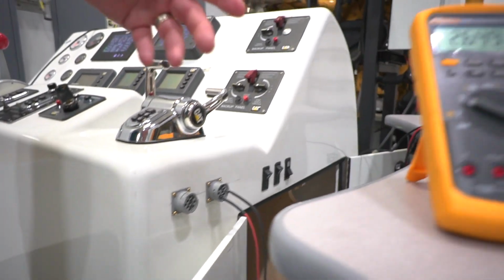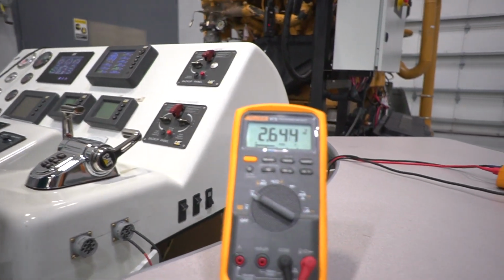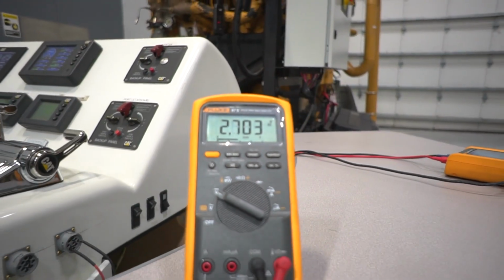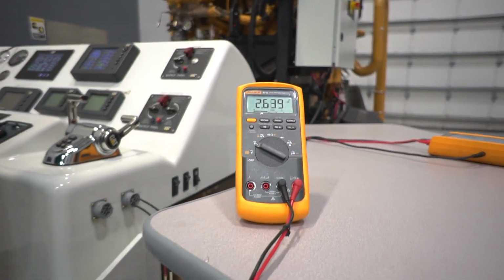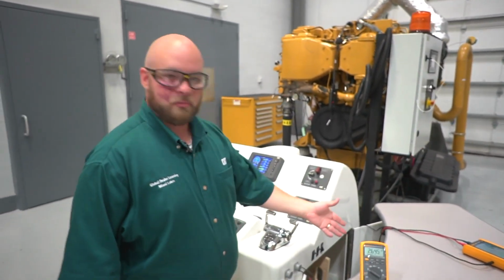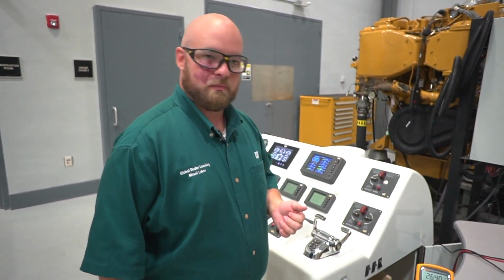And what do we see up here for voltage? I see 2.6 volts. That is above 2.5 volts. That's what we said the CAN positive should read, an average of above 2.5 volts. So we're seeing that here. We're seeing the voltage that we would expect to see.